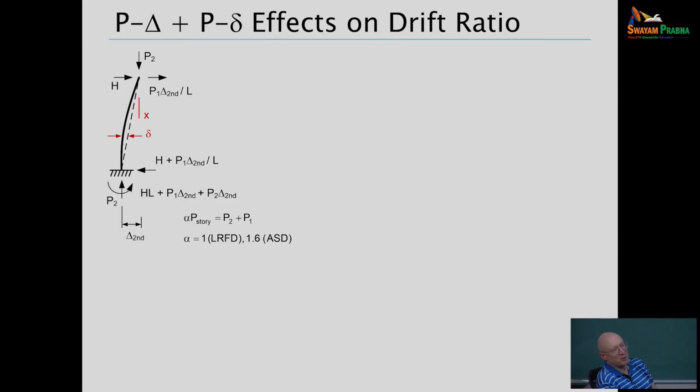So if there's no axial load, there's also no P small delta because there's no P. So the chord is between the deflected member ends, right? And then, because we have bending in the cantilever, the reference axis of the cantilever is offset from the chord at different positions along the length, right? If it's just a horizontal load, then yes, it's a sway problem. If there's no P, there's no P small delta, correct?